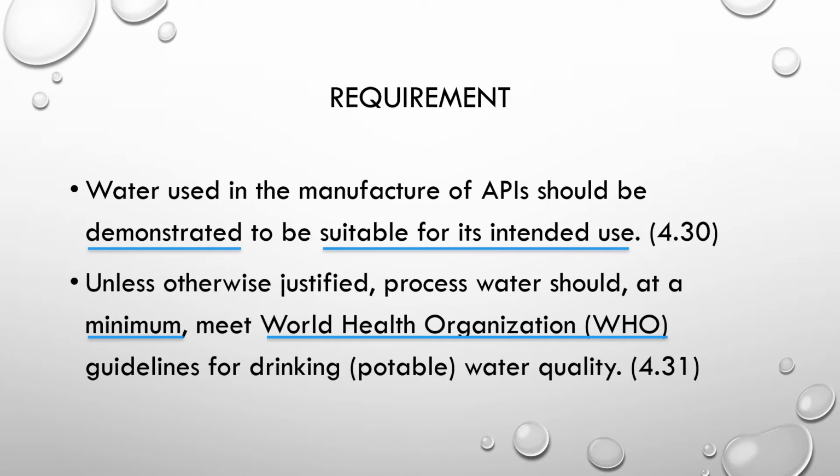You have to evaluate the data statistically for consistency. Statistical evaluation may include parameters like CP, CPK, moving range charts, etc. You have to document this evaluation data to establish the objective evidence for using this quality of water.